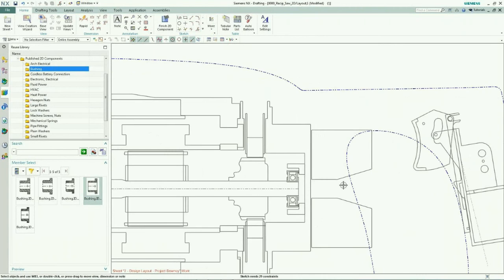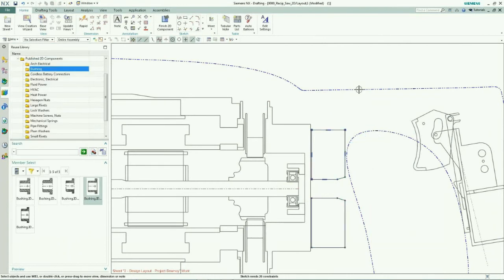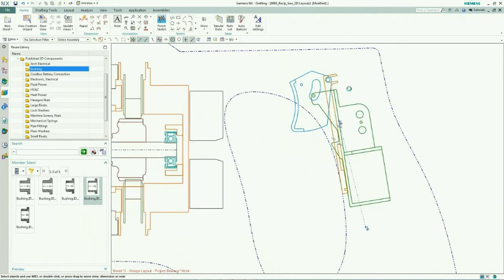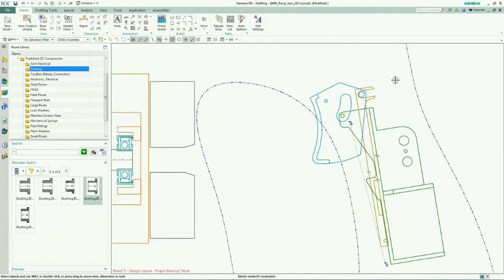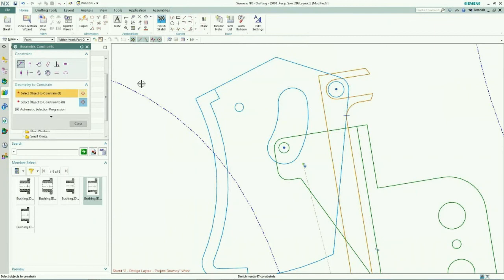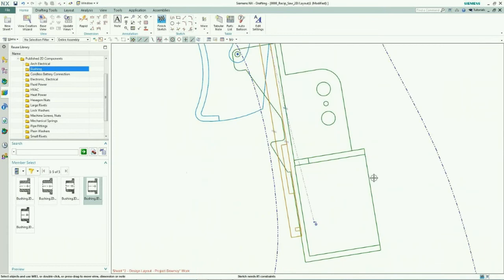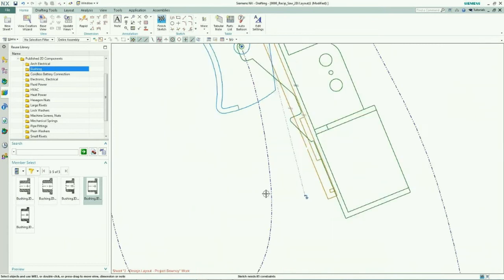We're going to finish up a little bit of an edit over here in the end of this bushing area, shorten that down, and then change focus, make a different component active. And as you can see, this particular component is actually a sub-assembly. It's the trigger assembly that controls, obviously, the amount of electrical applied to the motor. And this whole assembly can be moved around or edited individually. We can move that arc center down to a reference line. Now that becomes a pivot point, and we can just quickly drag the orientation of our trigger